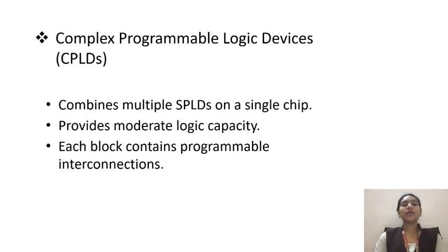So coming to the second type of PLD, complex programmable logic devices, CPLDs. These CPLDs are used to combine multiple SPLDs on a single chip. As we have learned, the multiple SPLDs, which are PROM, PLA and PAL, are combined in a single chip, and it provides moderate logic capacity, and each block contains programmable interconnections.